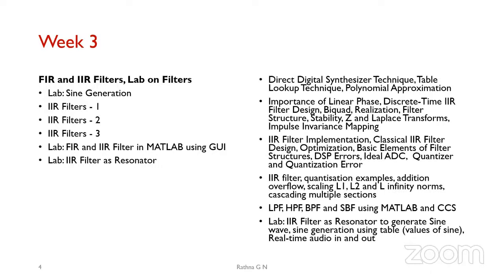One is sine wave generation. You can use the function to generate your sine component, multiple sine waves, and then see how you can eliminate them in your hardware basically, or the simulator you are using. And then any of the filters, low pass, high pass, band pass or band stop filter, you can look at it. Most of the time band pass and band stop we use for eliminating certain line frequencies.